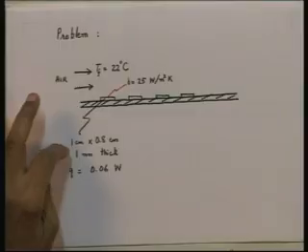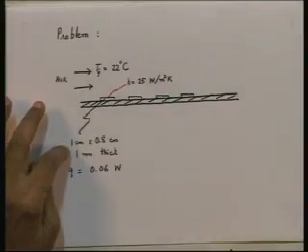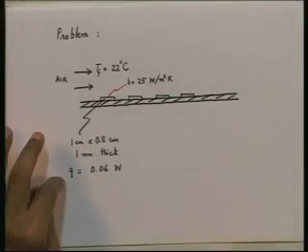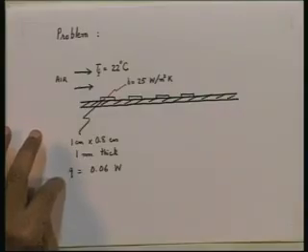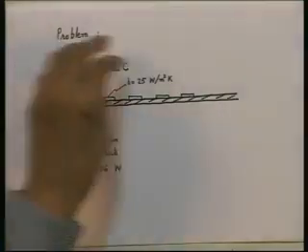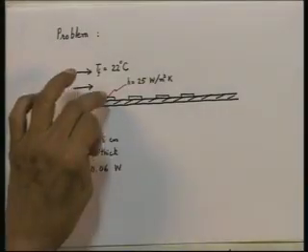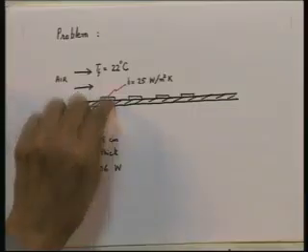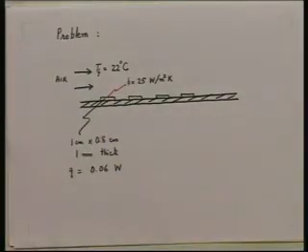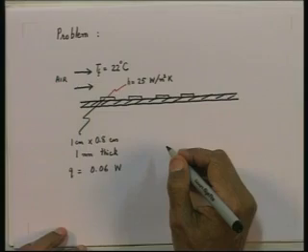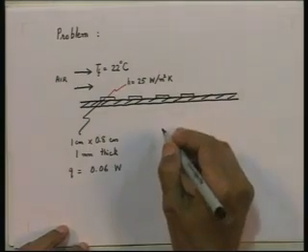So, you know the dimensions of each of the chips, you know the rate at which heat is being generated in each chip, the temperature of the air which is flowing over the chip to keep it cool, the value of the convective heat transfer coefficient at the surface of the chip. That is given. We do not know enough theory of convection. So, instead of calculating it from any equation, I am just giving you a value of H, saying take it to be 25. Says calculate the temperature, surface temperature of the chip.